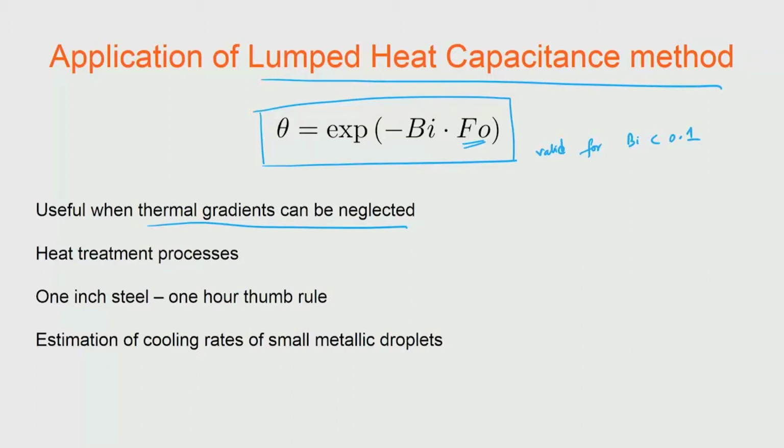Now, in heat treatment processes, normally we need to estimate how long it takes for us to heat up and cool down the materials, because that is the time that we need to give, which cannot be counted in the isothermal holding. Depending on the size, these durations can be significant. We can also estimate those durations using the lumped heat capacitance method, and where those durations are large, it means that the sample is too large or the thermal conductivity is too poor. So, we must take these transient effects into account.